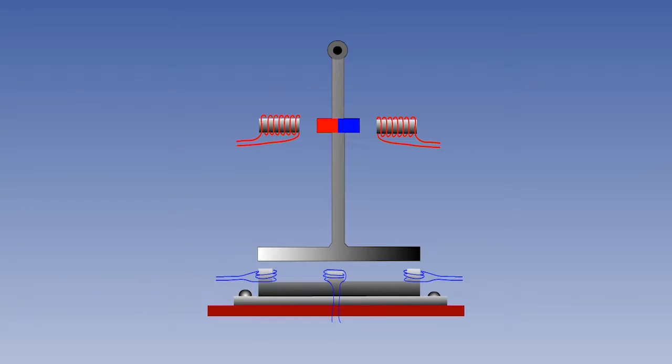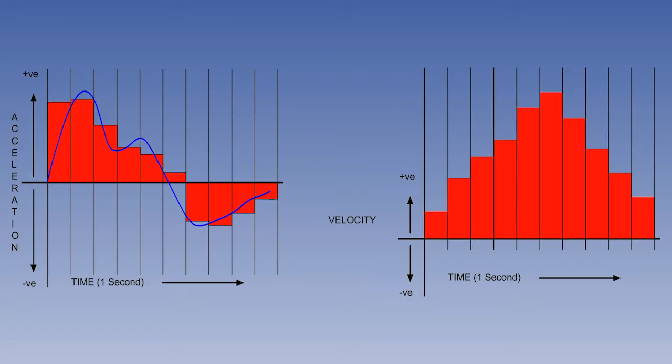Let's summarize the whole lesson now. There are various different forms of accelerometer, but the pendulous E and I bar type is a fairly common one. The actual mechanization does not need a long vertical bar, and practical accelerometers are usually a rectangular shape, with the long side horizontal. Integrators convert a rate of change over a period of time into total change over that time.